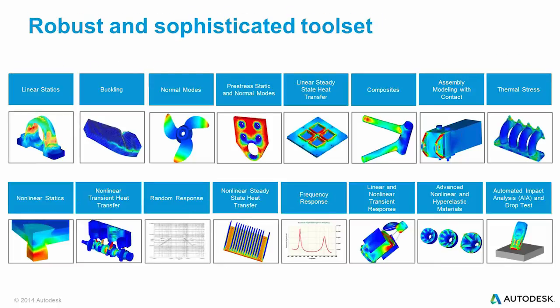If you're familiar with products like Inventor Simulation, that's very limited in that it can only do linear statics and modal frequency. Linear statics will allow you to apply a load, assumes the stiffness is constant, and gives you deflections, stresses and strains.